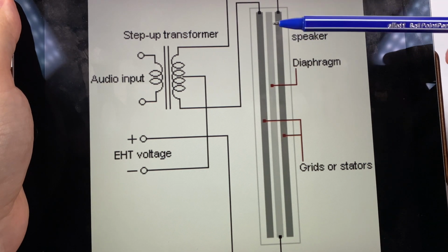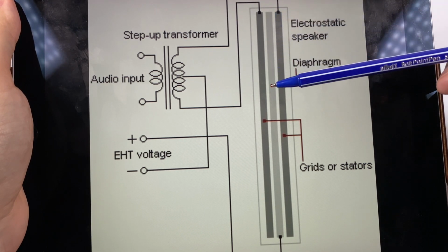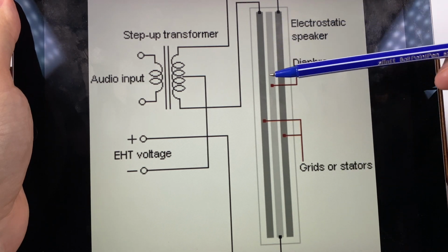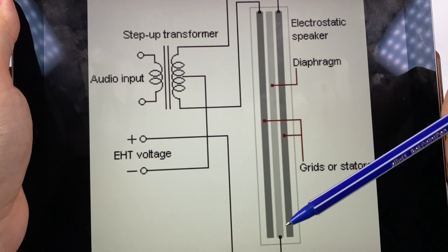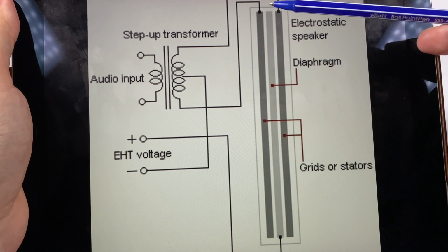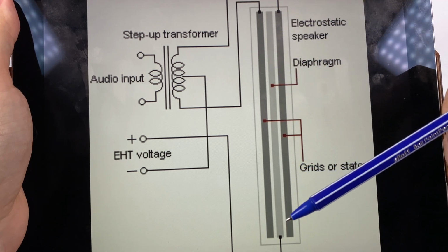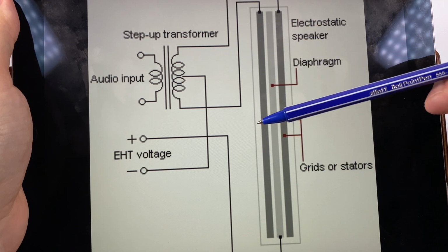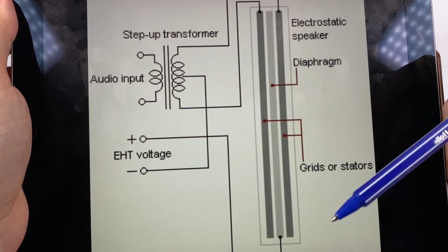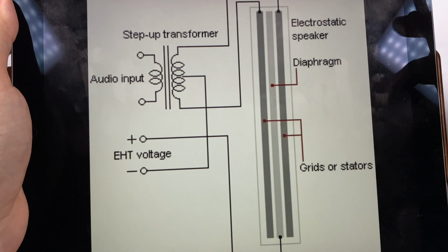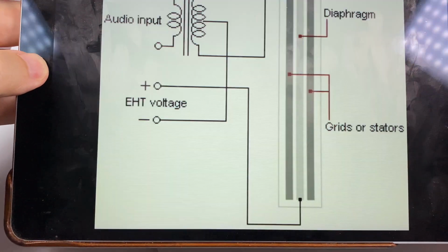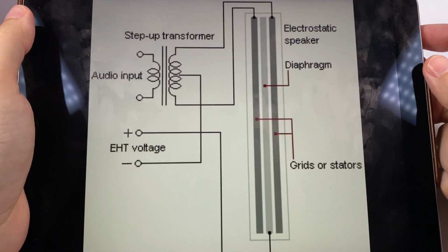The plus of this schema is that we can make this film really thin and really lightweight, because it's just a few nanometers or even micrometers thin, without anything else. And it just vibrates in this static field with high speed, so it's perfect for the high frequencies. It's pretty good for the mid frequencies, and this schema also works pretty well for low frequencies, but actually